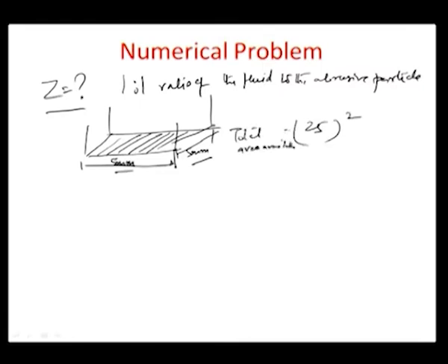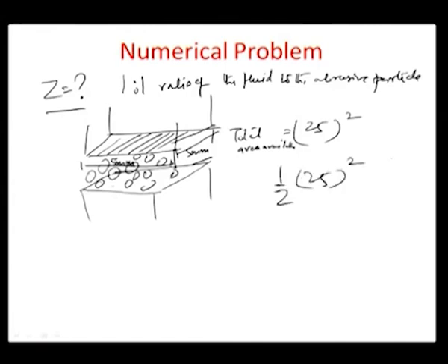available, and this area has to be flooded by a slurry between this and the workpiece surface which is situated down here. So, this whole volume has to be filled by a slurry which essentially contains these particles in the ratio of 1:1, meaning thereby that 50% of this area, half of this area, needs to be inundated with particles, and the particles, as you know already, have an average grain diameter d with an area of pi by 4 d squared, or pi (d/2) squared, pi r squared.